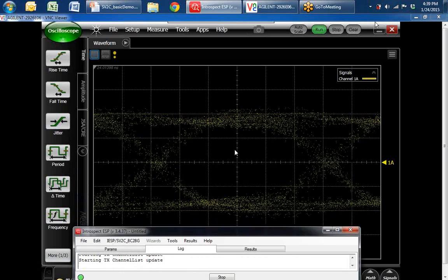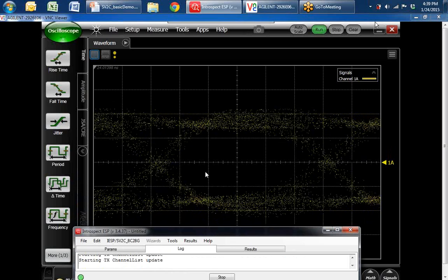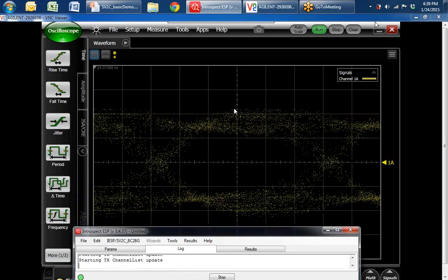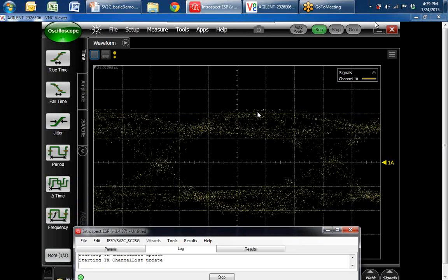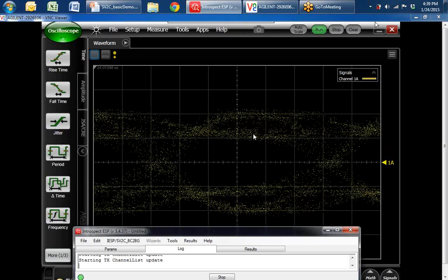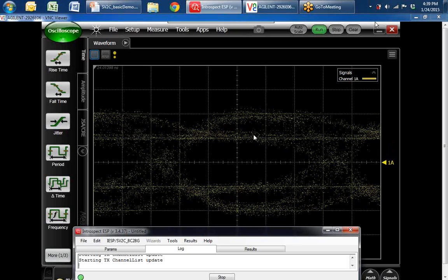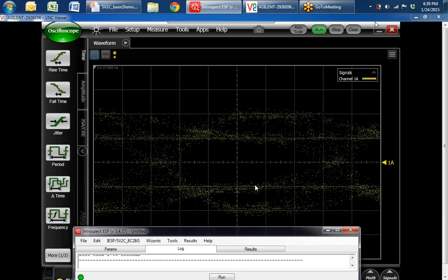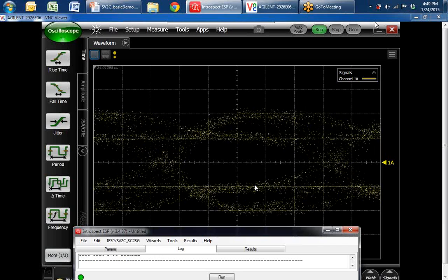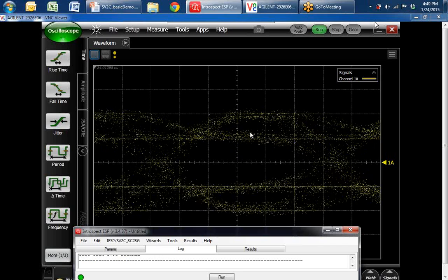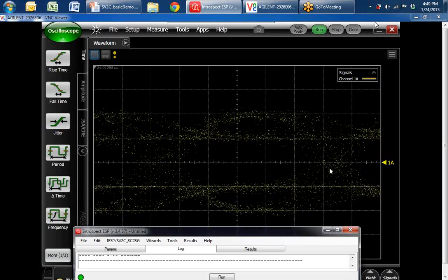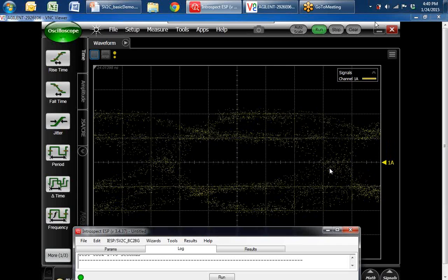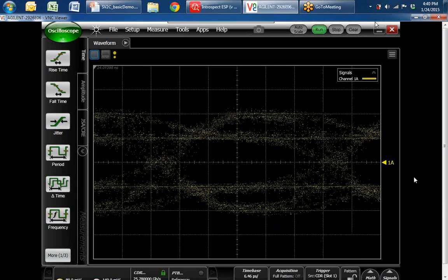And so you can see that the scope is updating every second. The main cursor tap is staying at the nominal location, and then the post cursor tap is decreasing. And what we're seeing here, we're now settled at a certain value that I've chosen arbitrarily in this quick demo. But you can see that the eye diagram is still very smooth and very linear, which means that the channel out of the SV2C is also linear.